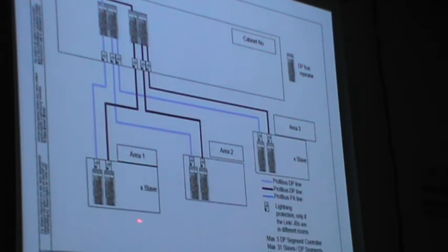So in total 32 devices can be used for one cable, and the cable terminator on the DCS side is only one. So the maintenance part is almost reduced. There is no maintenance about the cable. This is the advantage with Profibus.